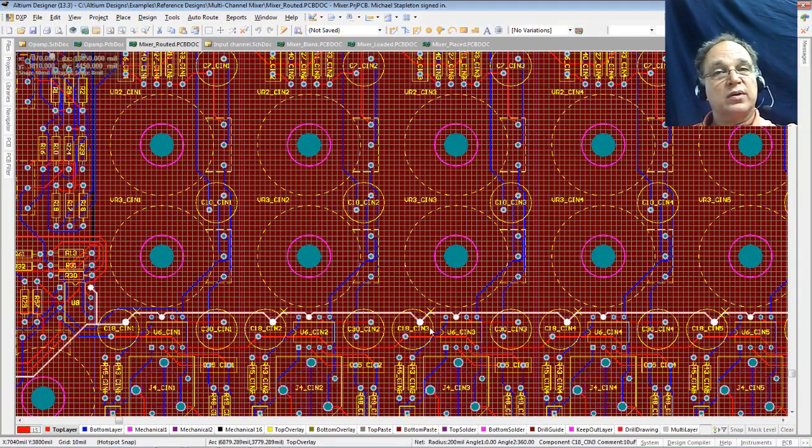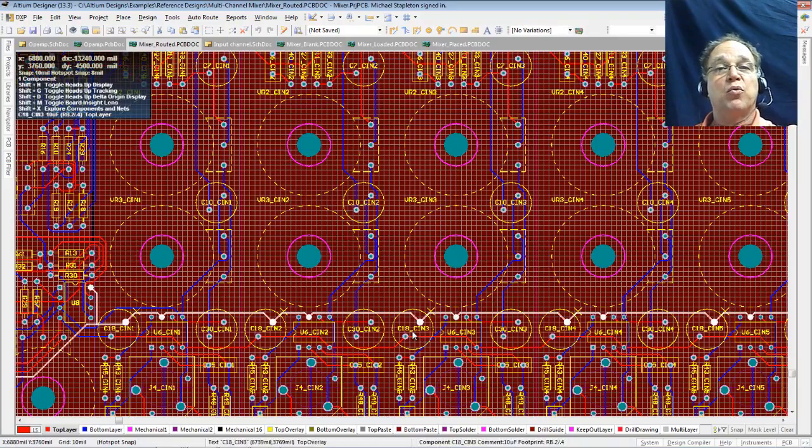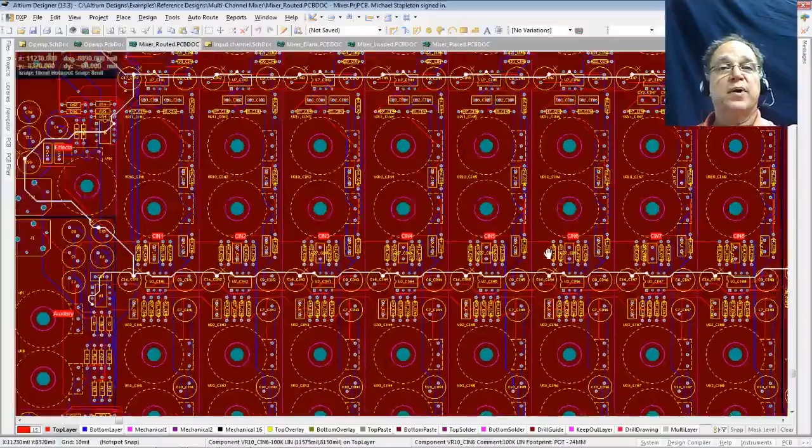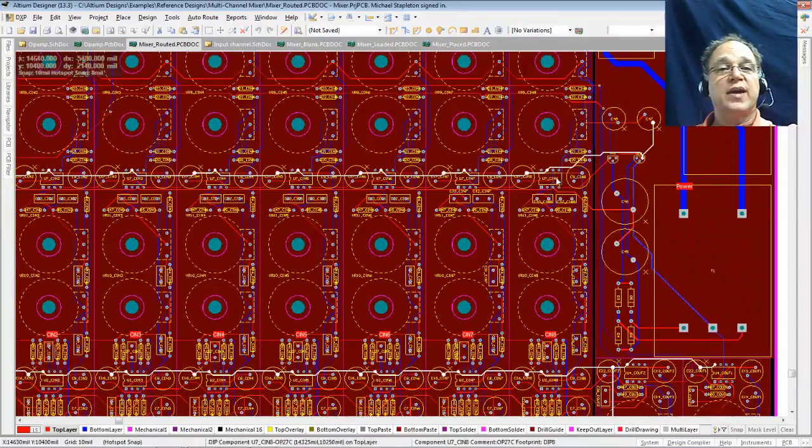It's a smart engineering idea on most designs to put a bypass cap right next to every active component on your circuit board. As you can see on this board, they have bypass caps on every active component because I have to deal with the inductance and the DC resistance of this trace all along the entire board.